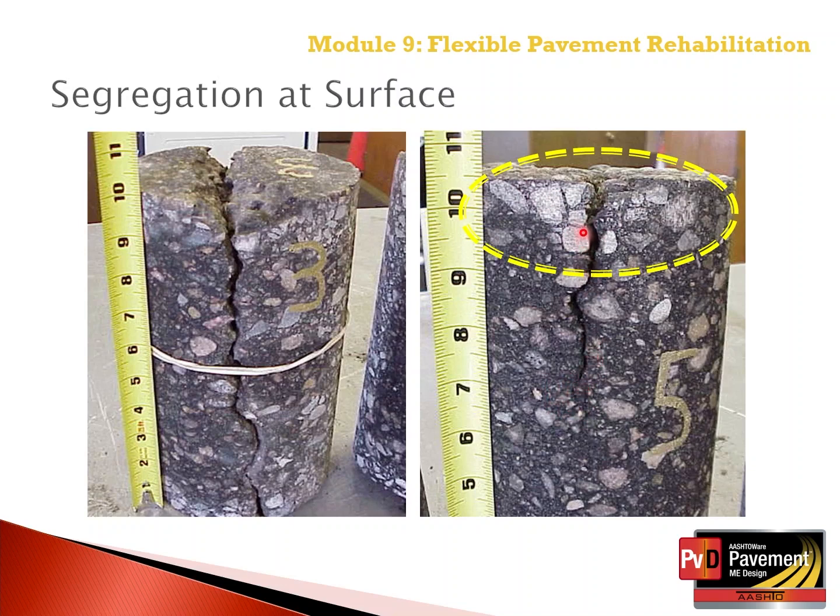It generally varies from about 1 inch to about 3 inches below the surface, but it's caused by longitudinal segregation at the surface of the asphalt pavement. While this area has cracking throughout the entire depth, both top-down as well as bottom-up fatigue cracks, but also exhibits very severe crack deterioration at the surface.